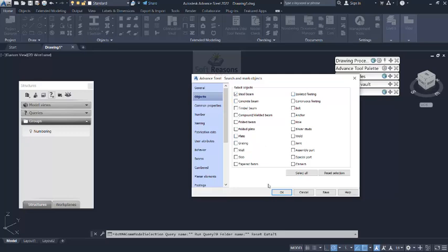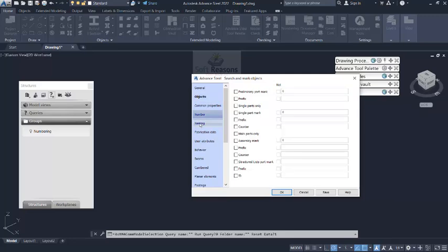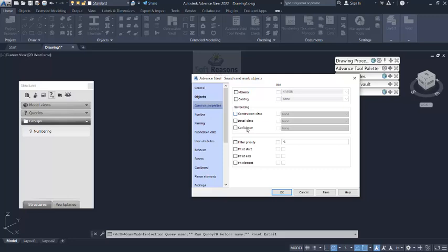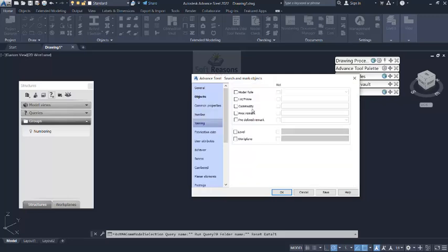So I select beam. Having selected the beam, I'll come to the number, and in the number you can also change the mark and the prefix and the rest of that, but that is not necessary. Then you can go to the naming right there. In the naming, the model role is very, very important. You have to get it activated. Having that activated, we can now proceed to the provisions, and then we will look for beam, because what we selected there is beam.